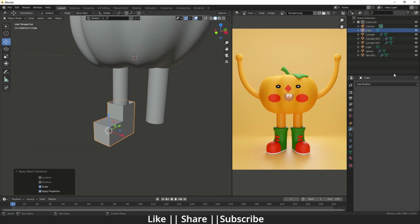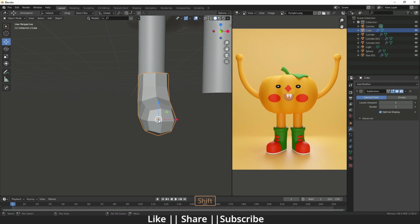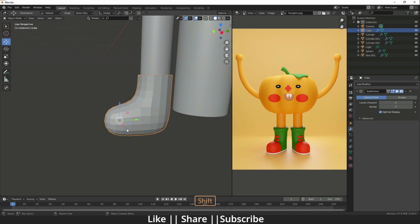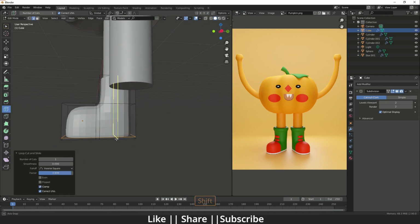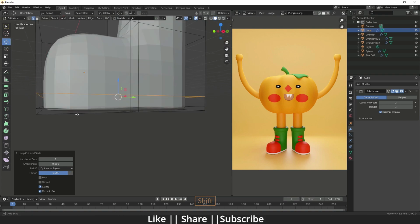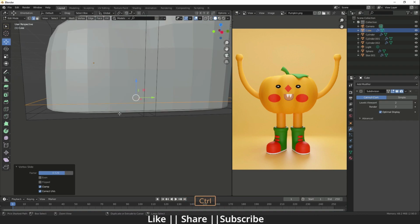So then I'm just going to add one subdivision modifier pressing Ctrl 2, and you can add it from here as well, so it will look like this. So make sure first of all to increase the viewport level. So first an edge loop I'm just going to add here, should be here, and then I will add one edge loop here as well, and then I'm just going to keep it a little bit downside. Then I will do Ctrl B for the bevel of this edge and add one edge in between here,